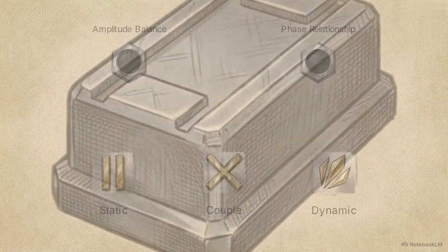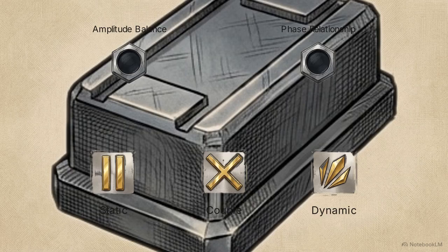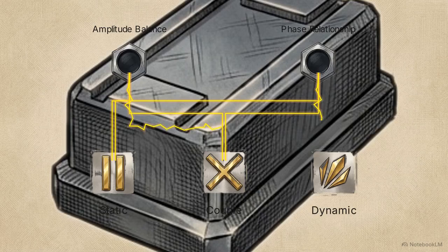This diagnostic matrix connects those symptoms to their geometric cause. If amplitudes are equal and phases are in sync, it's static. If amplitudes are equal but phases are 180 degrees apart, it's a couple. If everything is unequal and out of sync, it is dynamic.